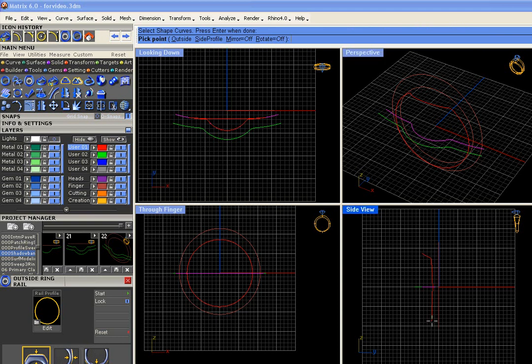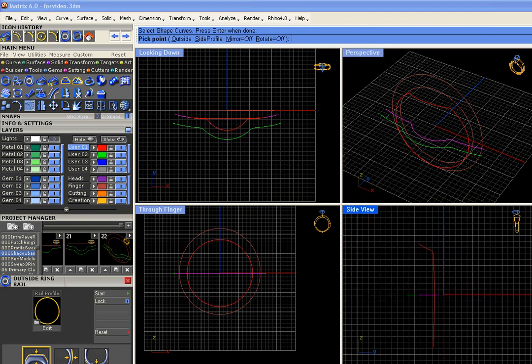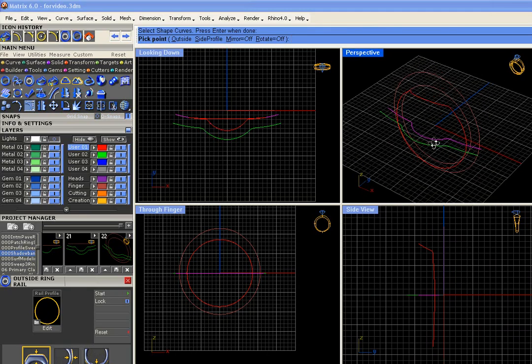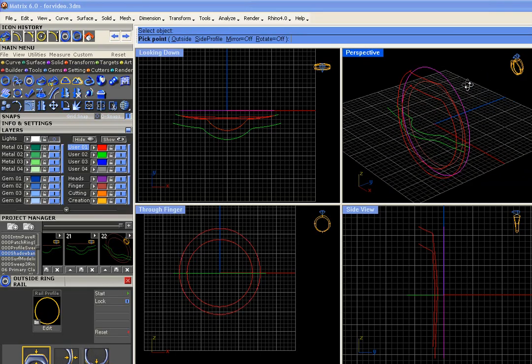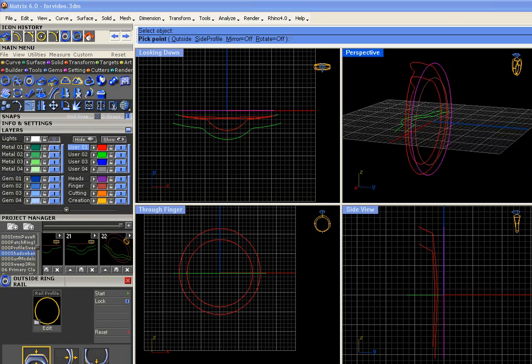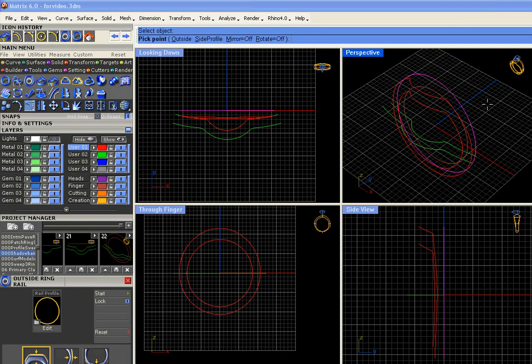Okay, and the first thing it does is to match with the finger rail using the curve from two views command. So here's the finger rail shape. You can see the new curve in red, and it also follows the curvature of the shape curve that we selected. Okay, we also need an outside one for this. The best way to control this shape is with 4 rails. So we go and select the outside option, the outside finger rail, and there are 2 of them. Okay, press enter